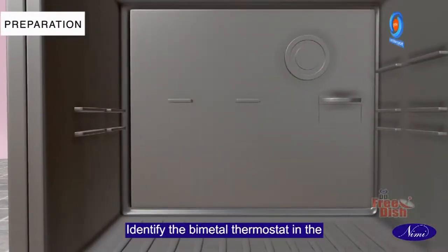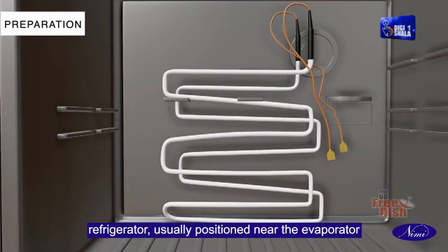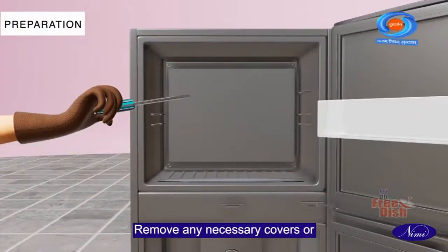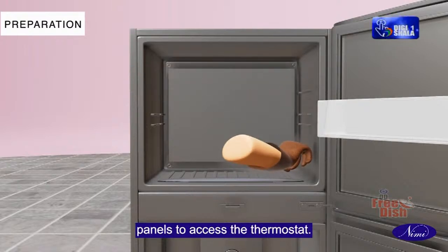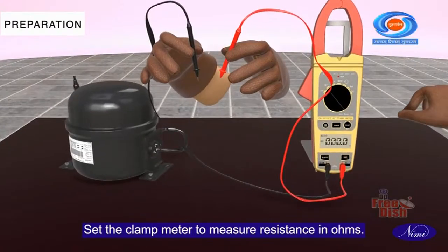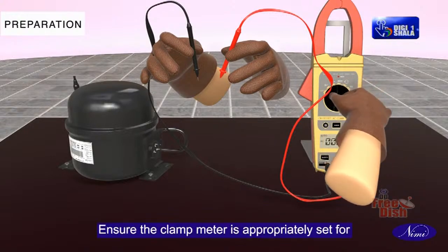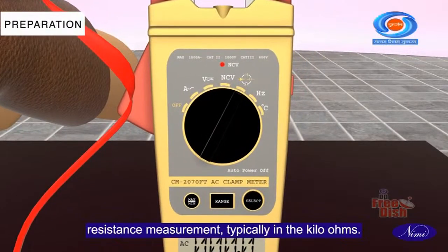Identify the bimetal thermostat in the refrigerator, usually positioned near the evaporator coils or in the freezer compartment. Remove any necessary covers or panels to access the thermostat. If applicable, unscrew or remove protective covers. Set the clamp meter to measure resistance in ohms. Ensure the clamp meter is appropriately set for resistance measurement, typically in the kilo ohms.